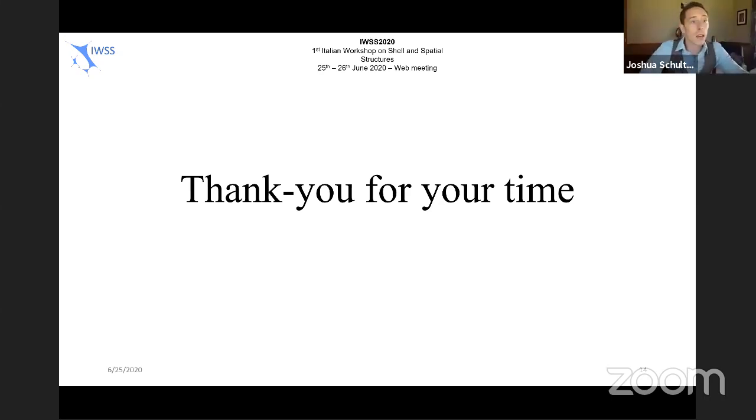Yeah, so what that goes into is one of the main assumptions which we're working on modifying, because right now it's a pretty simplistic approach, but it gets us within about 5 to 6% of our experimental results. And so what we're doing is we're assuming that all those longitudinal layers are taking the axial loading, and then the inner layers are only taking shear as a function of the shear stress. And so as you get thicker with that, two things happen. One is that you start to get some actual interlocking between the members, even though they're not side glued.